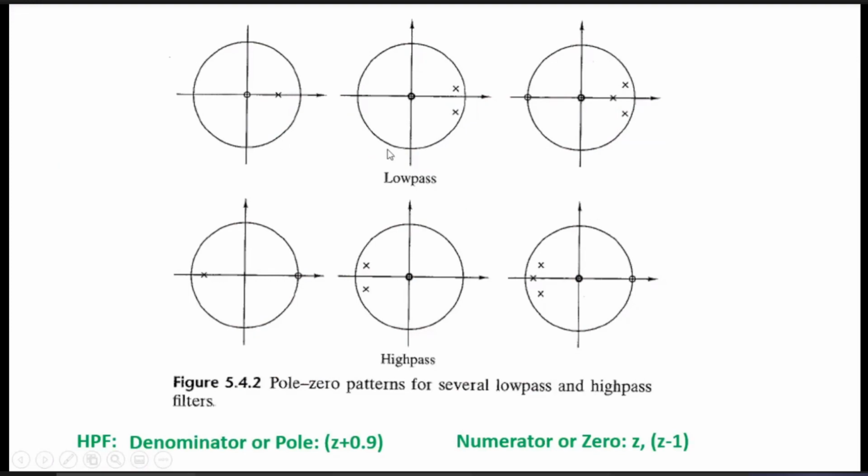That low pass filter, the top diagram actually shows the locations of poles and zeros for low pass filter. लो पास फिल्टर में क्या हो सकता है, ये इस पोजीशन में है, देखो राइट साइड में, मतलब पॉइंट वन यूनिट सर्किल के नजदीक है, और कॉम्प्लेक्स कॉन्जुगेट भी हो सकता है, और यूनिट सर्किल के नजदीक है। ये सब पोल्स, मतलब पॉजिटिव वैल्यू है z का, ठीक है, z का पॉजिटिव वैल्यू that corresponds to low frequency at which the gain is high, and there are two zeros at z is equal to 0 origin and at z is equal to -1, ठीक है।